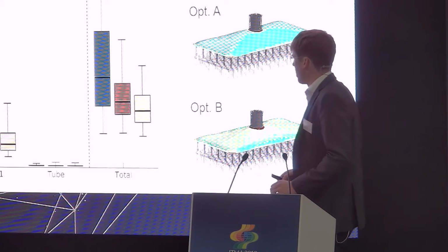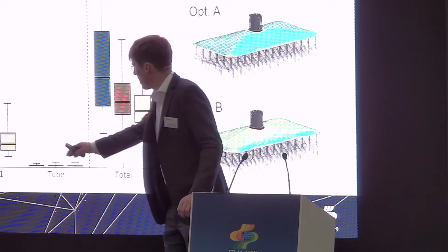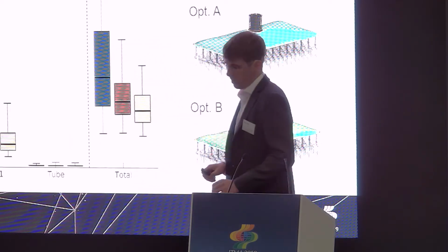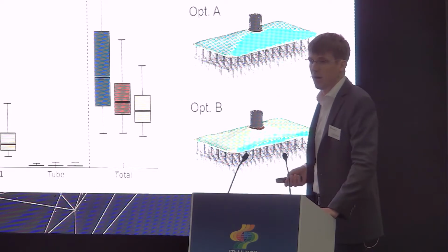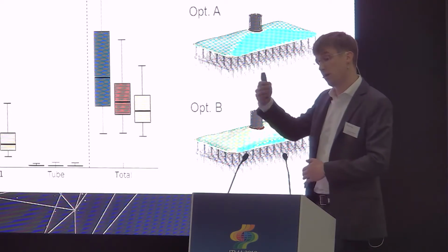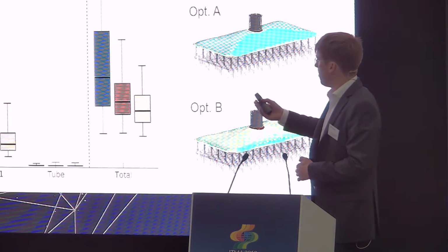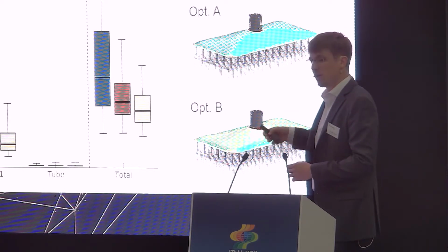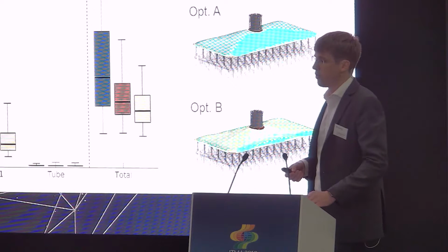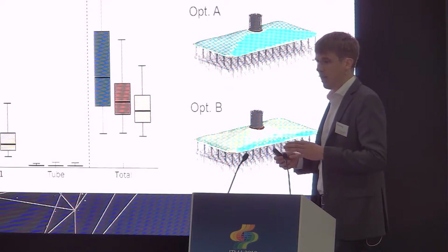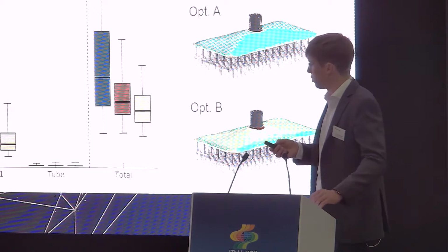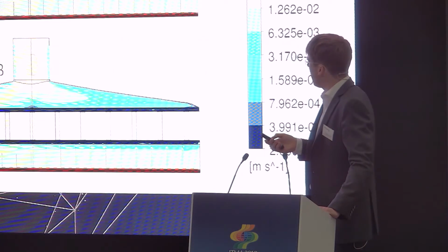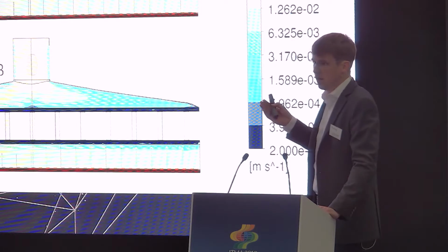And you can see that it was possible to greatly reduce the residence time in cavity 1, and therefore also reduce the total residence time, and also, of course, the spread of residence time in the spin pack. And doing this with the wall shear stress criterion in an optimal way, such that the pressure is not influenced too much, we can check this here.